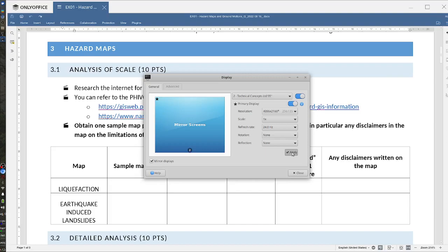Okay, so peak ground acceleration is just equal to 10 raised to the quantity of 0.41 times magnitude minus log 10 of the quantity of R plus 0.032 times 10 raised to 0.41 magnitude, minus the quantity of 0.00334 times R plus 1.3.